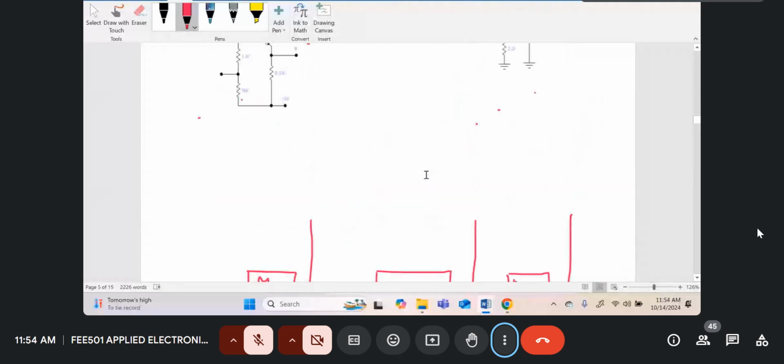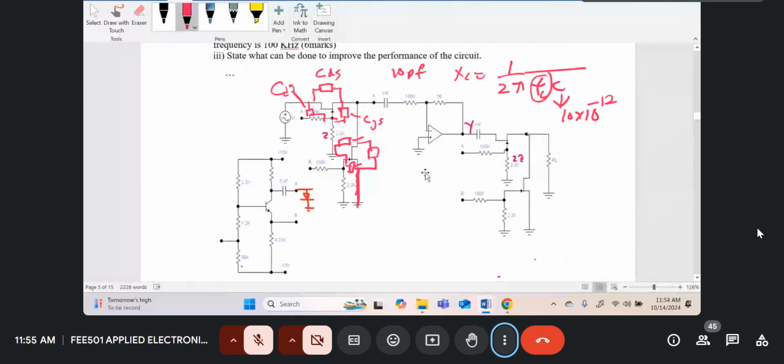So finally, most of the questions in the exam will be to find the overall error of a chopper stabilized amplifier system. A chopper stabilized amplifier system has got 3 parts. Like this example over here, this is the modulator, and we've got an identical circuit over here, which is the demodulator, and this circuit in the middle comprising the op-amp is your AC amplifier. In this case, the capacitor to your AC amplifier is 1 nanofarad.